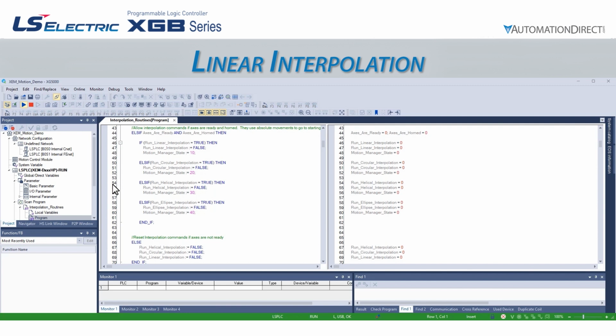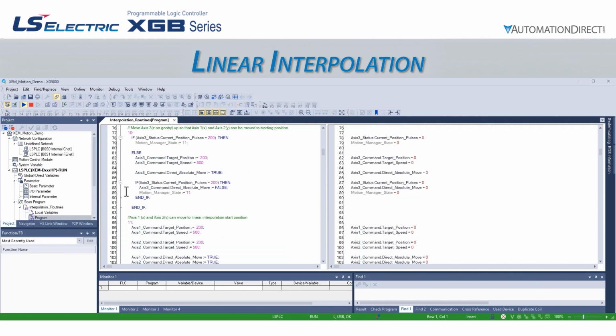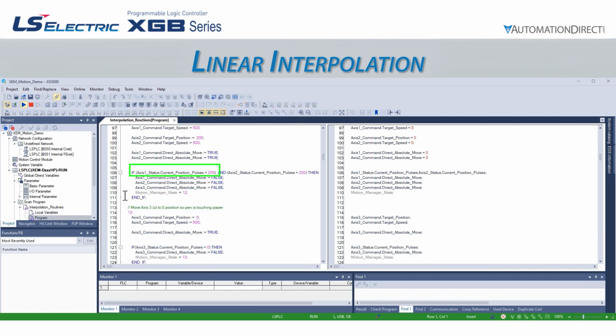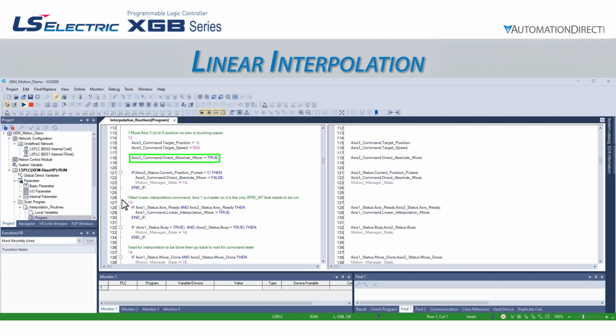This program has been set up to use the user variable Motion Manager State as the index for a state machine. We are doing a linear interpolation, so we see that if the axes are ready and homed, and we make the run linear interpolation bit true, we will execute Motion Manager State 10. Starting with line 76 of the code, we see that motion states 10, 11, and 12 are all execution of direct start commands to position the 3 axes for the start of the linear interpolation.